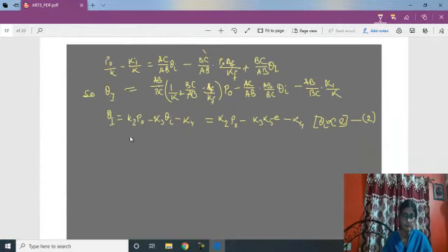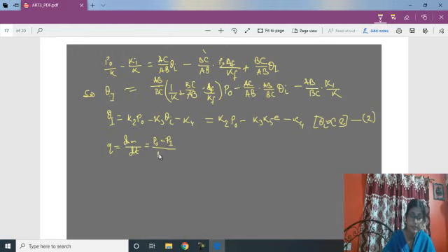So the mass flow rate through this integral restrictor, dm/dt, equals the nozzle feedback pressure minus the integral bellows element pressure Pi, divided by the restrictor R. Say this is equation number 3.